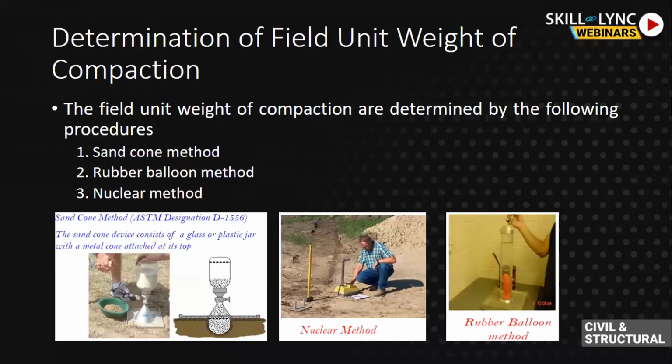One of the most important factors is error determination. In the sand cone method, voids under the plate, sand bulking, compacted soil, and soil pumping could be the errors that lead to wrong determinations. In the case of the balloon densometer, if the surface is not level, soil pumping and voids under the plate will generate errors.